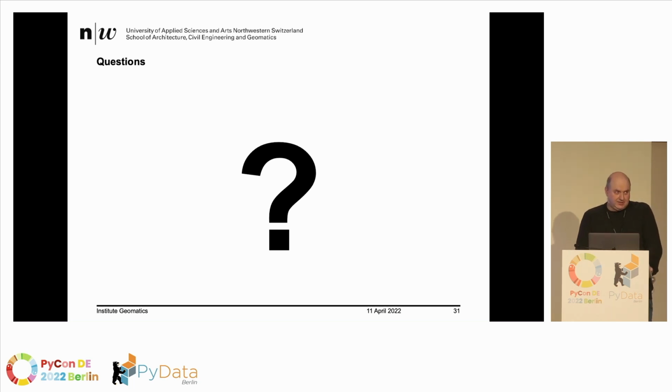Because it's basically the same. The problem is there are many city models available now, even textured. For example, Rotterdam has a wonderful big textured city model. The problem there is that often the texture size is really huge, so you have to find a way to reduce the amount, and you have to work with level of detail techniques. You can't just visualize the whole city in one part. So that's quite difficult. But it's basically the same thing. You can create OBJ out of that. Usually it's available in CityGML, and then you have to convert it. For example, you can use Python for that, of course.